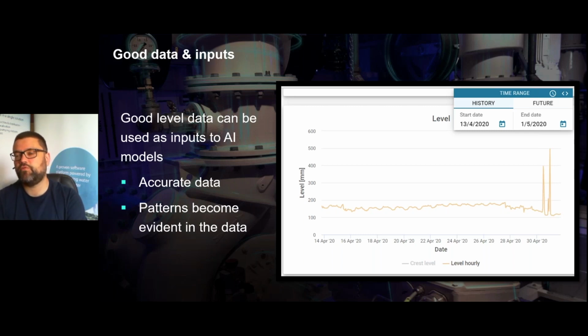We had a huge amount of rainfall, and you can actually see in this trend quite clearly that prior to that rainfall, there was a buildup of dry matter in the pipe. Big rainfall event, and the pipe cleared itself. And after that rainfall event, you can see the level in the sewer is lower. So you can see from this data, just from human interpretation, that there is the ability to pick up patterns. And that's what we're looking for in artificial intelligence.